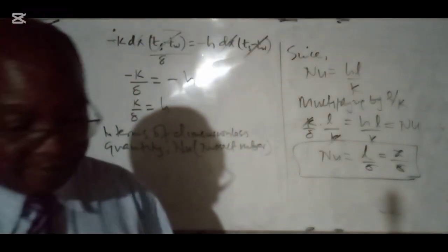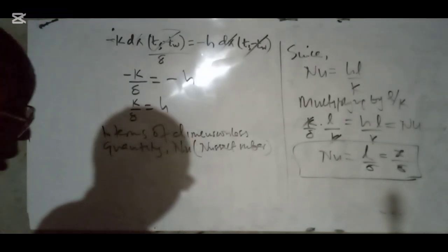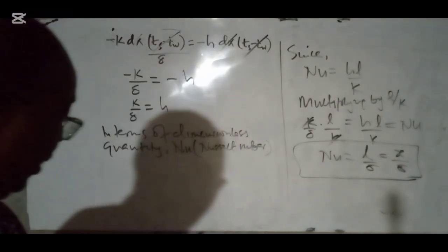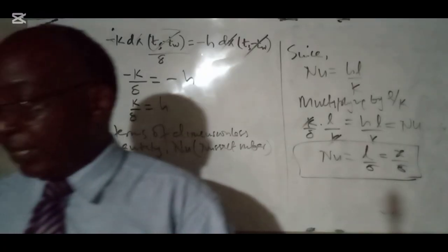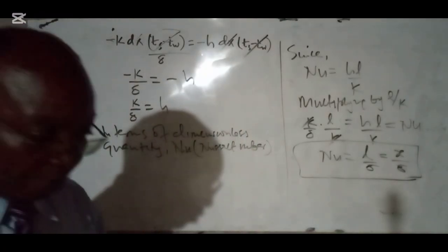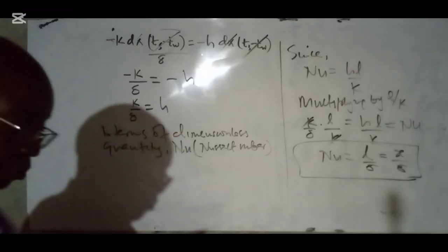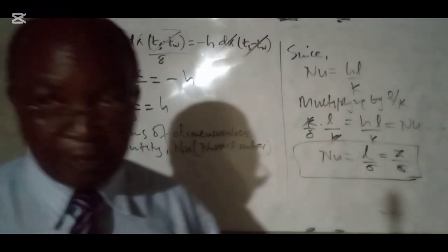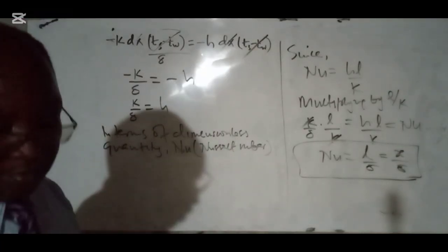The values are all tabulated, and somebody can access them and know the associated energy changes. Number two, it's important for us to note that when this condensation takes place in this laminar film, while it can move up or down, most of it will be because of viscous gravitational force as opposed to hydrostatic pressure or inertial forces. Very important for us.